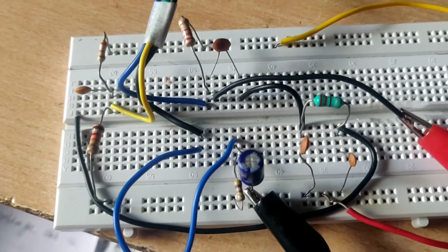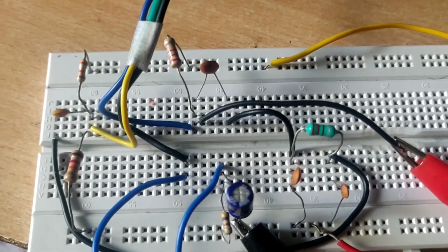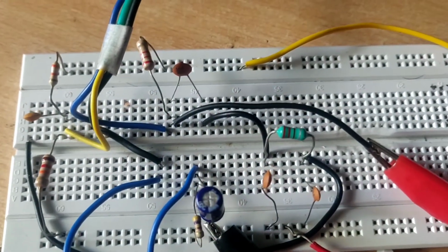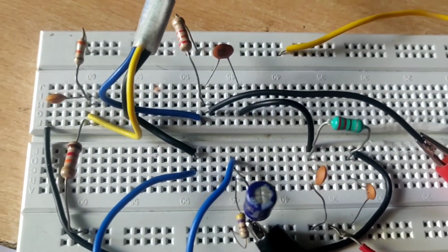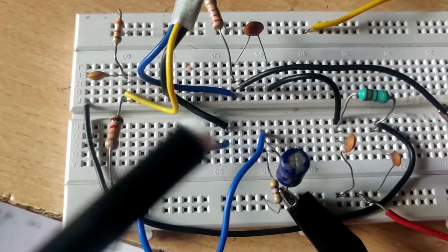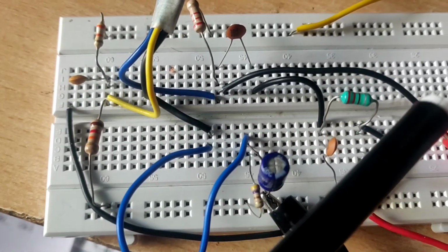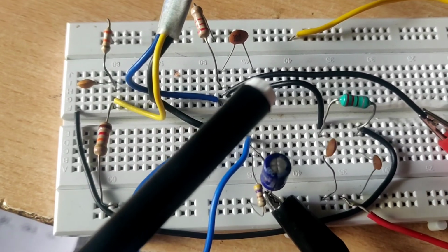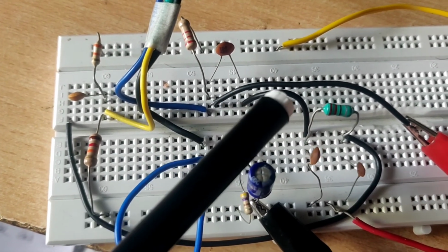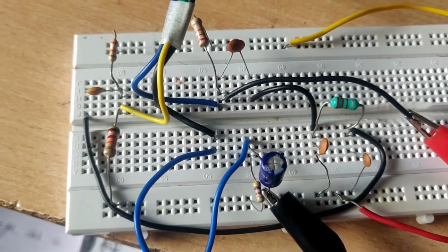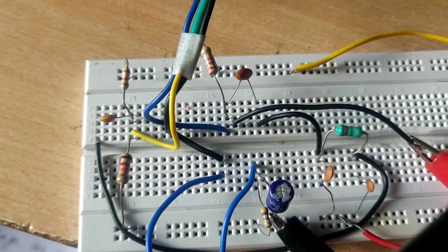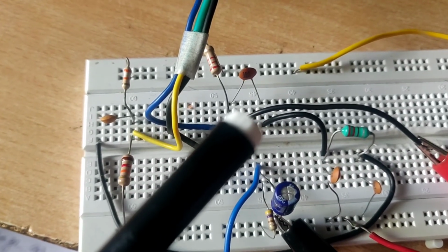So I assembled this circuit as per our diagram, and this part is an amplifier section, left part. This is an amplifier section, and this is the tank circuit, and the connection between the amplifier and tank circuit is this one, and one positive feedback wire is connected to this, and the output is connected to the collector of this.